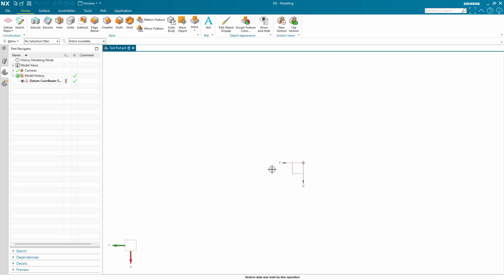And if I want to get back to my more, let's say, diagonal views, that would be trimetric or isometric, the home key is going to send me to a trimetric view, and the end key is going to send me to an isometric view. So those are really nice. Like if you're all wonky and you're upside down and out of the way, if I hit either one of those, it centers it and goes to that angle, trimetric or isometric, to allow us to see the part a little bit better.